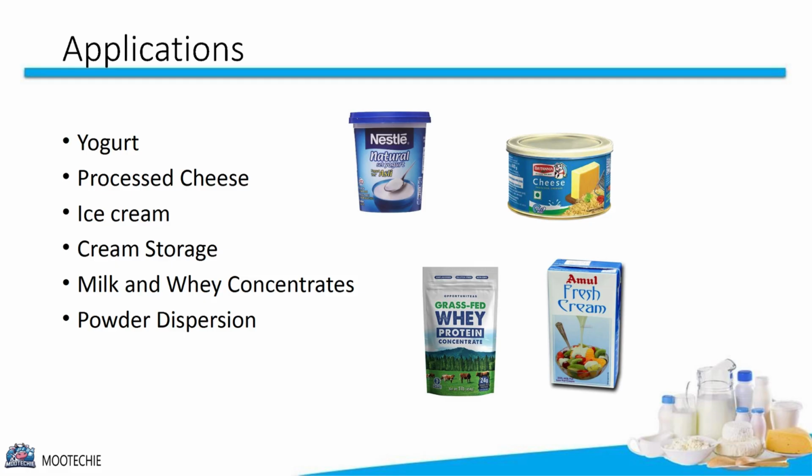Cream storage tanks require gentle agitation to prevent fat separation. Agitation is also necessary in tanks holding milk and whey concentrates to avoid settling. Finally, effective agitation is essential for the proper dispersion of powders into liquids.